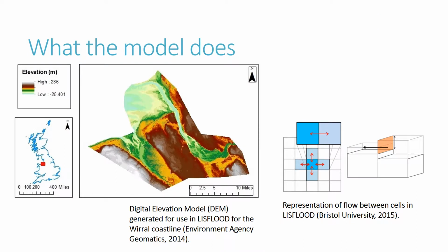The increasing availability of high-resolution topographic data acquired using airborne remote sensing, for example, light detection and ranging data, allows for more accurate representation of flood inundation. LISFLOOD operates over a raster or square grid of LiDAR data to predict the dynamic propagation of flood waves. Water moves across the grid from a user-defined boundary over floodplains. LISFLOOD simulates floodplain inundation in 2 dimensions by solving the shallow water equations which describe water flow. The model assumes that the flow between 2 of the grid cells within the domain is a function of the surface height difference of the 2 cells and gravity.